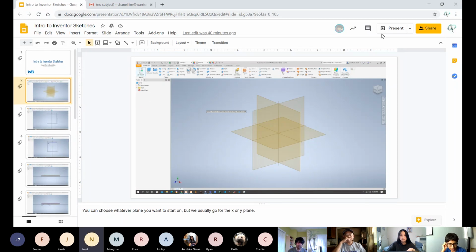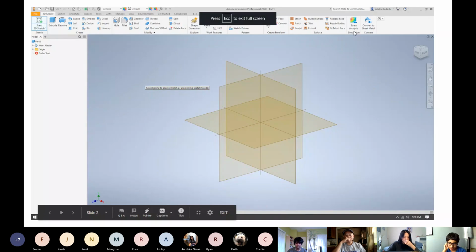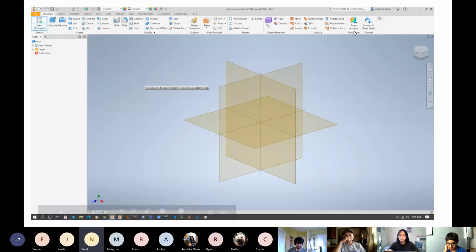I know we said earlier that when creating parts, most of the time XY is our go-to. That's not exactly a great practice. I know we've been doing it in the past, and quite honestly, we should probably stop doing that. The reason is that every time you place a part that you've made from a sketch, that part is based off of this original sketch, right?